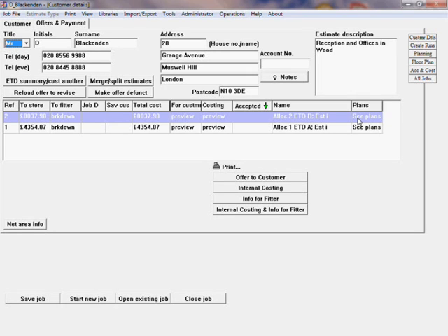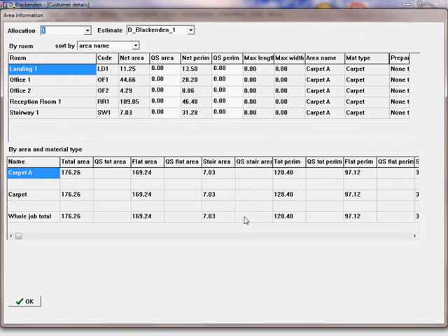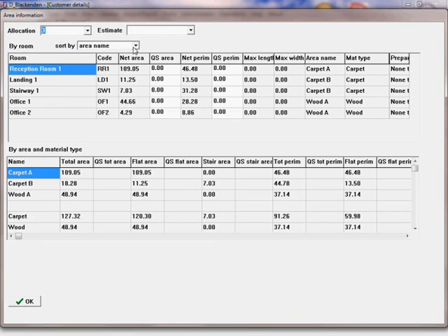For larger contracts, the prime contractor may mandate that the quote is formulated against the net areas, which the quantity surveyor has assessed. MasterPiece can provide a full presentation, as here, of all the net areas, as calculated from the geometry we entered by trace-around. It also allows for quantity surveyors' net areas to be held, to support the formulation of rates for the job against a quantity surveyor's net areas. You can also enter a room area as defined by the quantity surveyor in the request for tender documents, as this may have to be used to generate the rates required in the tender.